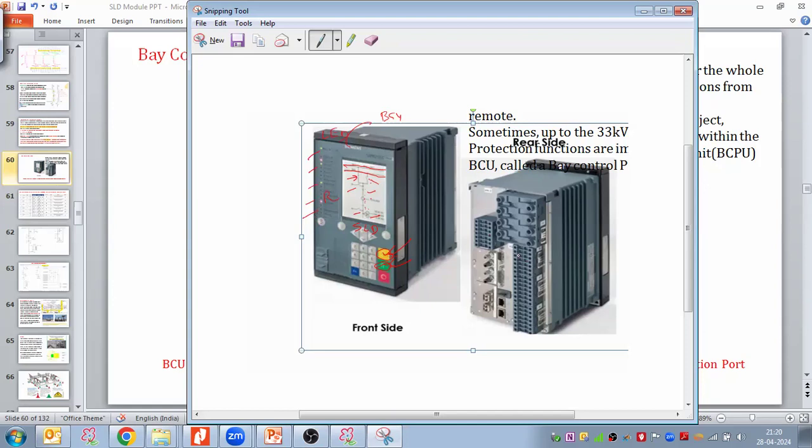All the equipment wiring is taken from here. We have a terminal block through which we can wire, and a communications port through which we can connect this BCU into communications, including to the substation SCADA. For criticals, hardware interlocking from direct contact from each equipment is used; it is recommended not to use only the auxiliary contact.